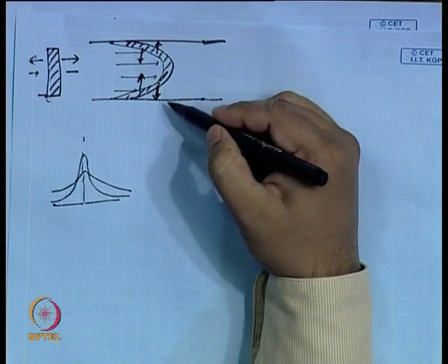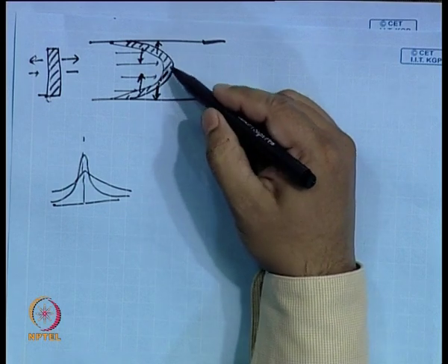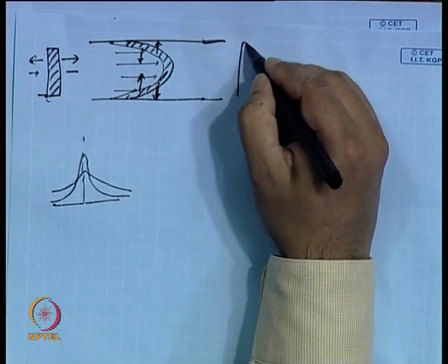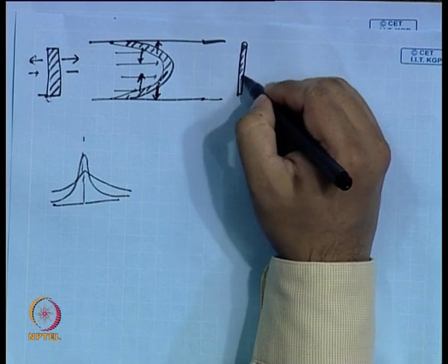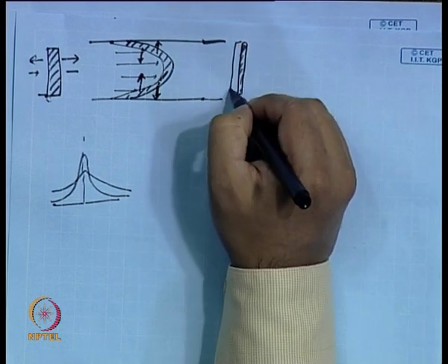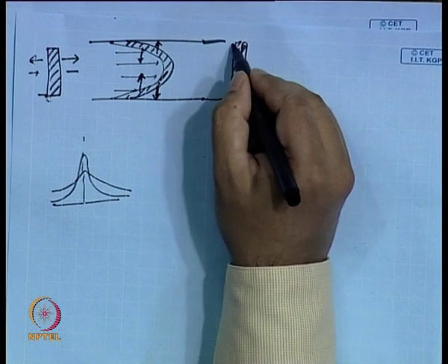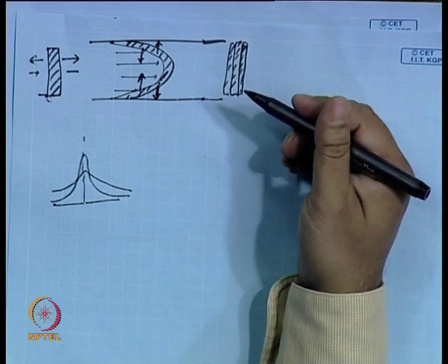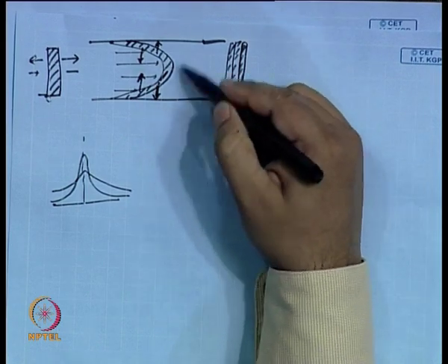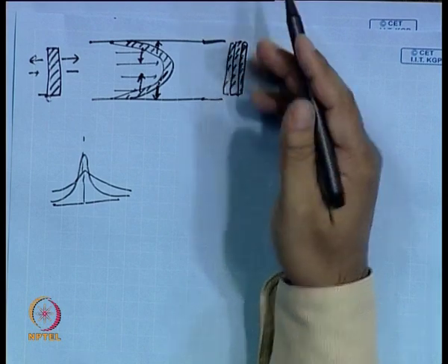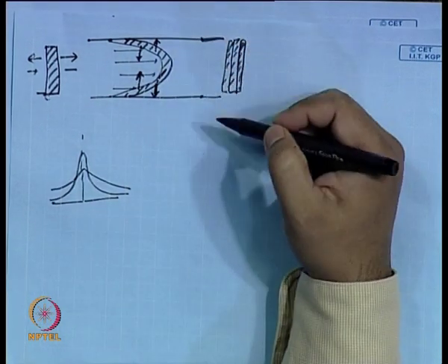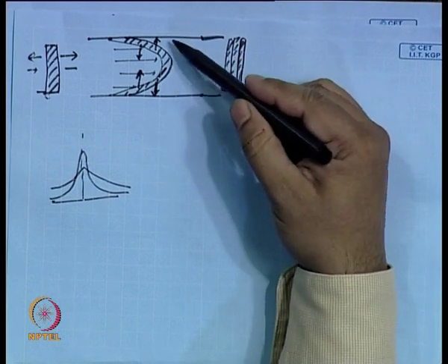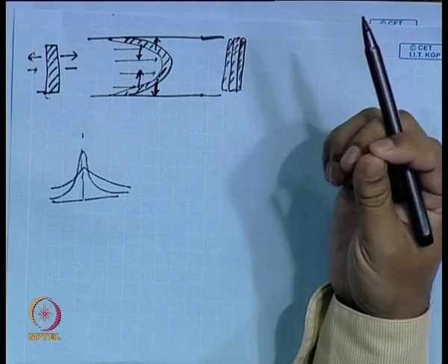Rather, at the outlet, you pick up a slice, measure the concentration, you pick up the next slice that you receive and measure the concentration, which is basically the average over the entire cross section. This is called a mixing cup concentration. It is like you take that slice, mix it and get the average concentration.